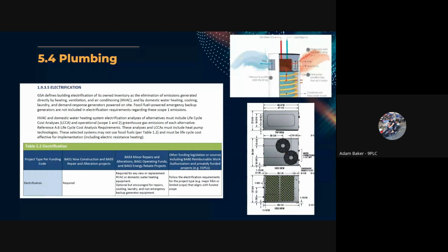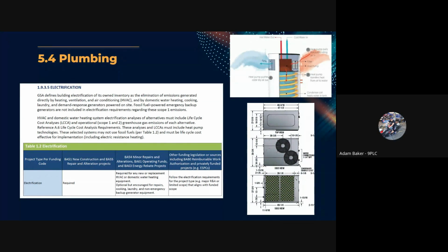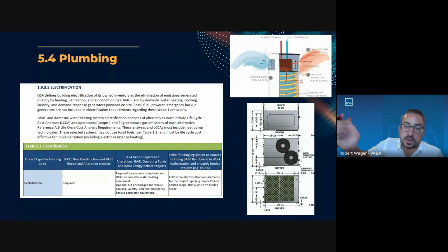Question is, if you have several fan coil units in the building and you have a condenser on the roof, are we required to have a two-way valve or three-way valve if the condenser has a VFD? If you're specifying a system that is ganging up multiple evaporators to a single condenser, typically those systems have their own specific components that come with it to isolate one over the other, so that the condenser can continue to operate if all fan coil units are not on at once.